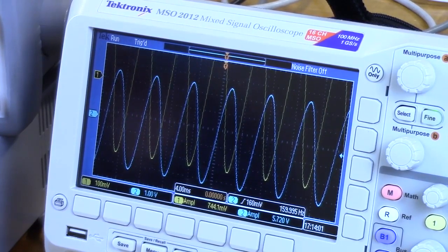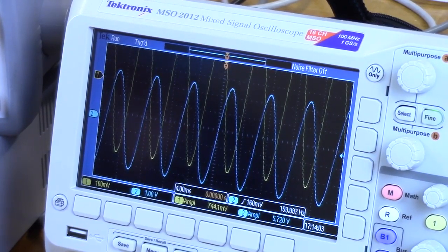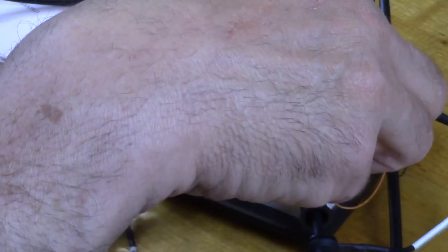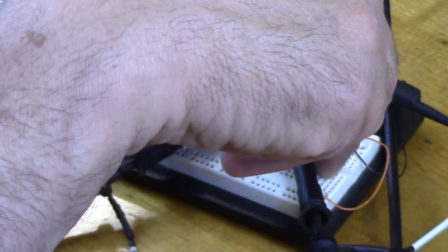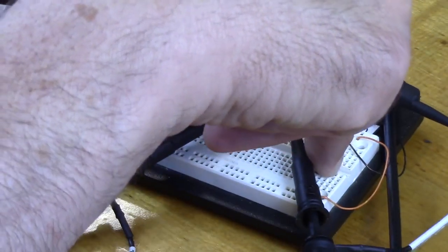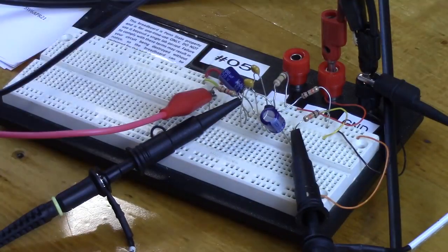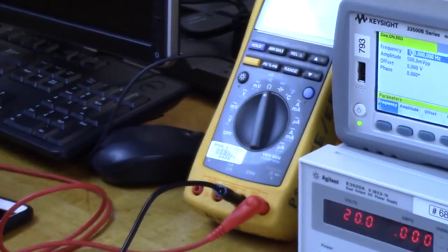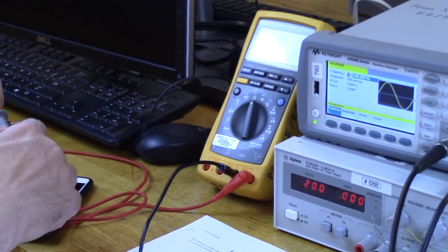So low frequency response is difficult to measure. Let's just take out the pot for R2 and measure it, and that should be the last thing we need, so you'll be able to get a value for RB. I'm going to disconnect the power supply and turn this to ohms, and we'll see what we get for the resistance of the potentiometer.